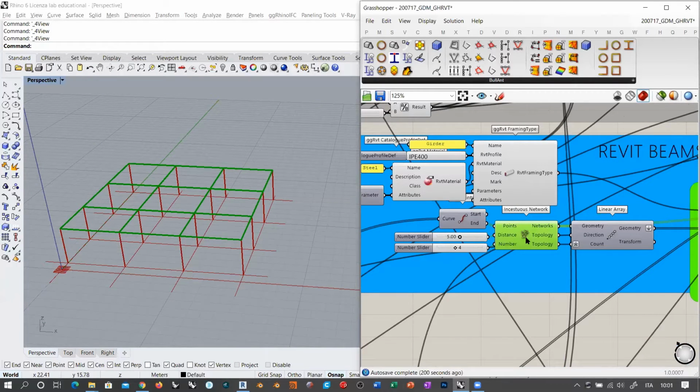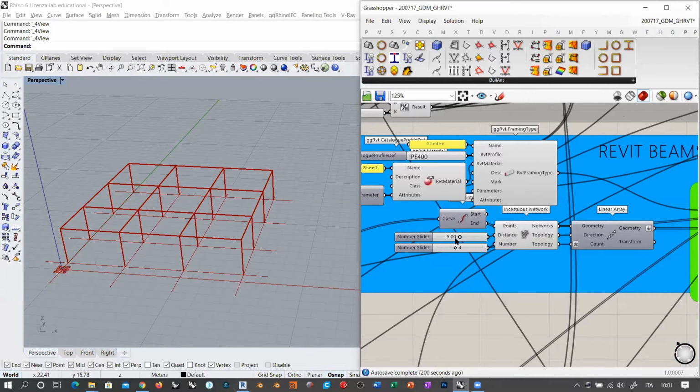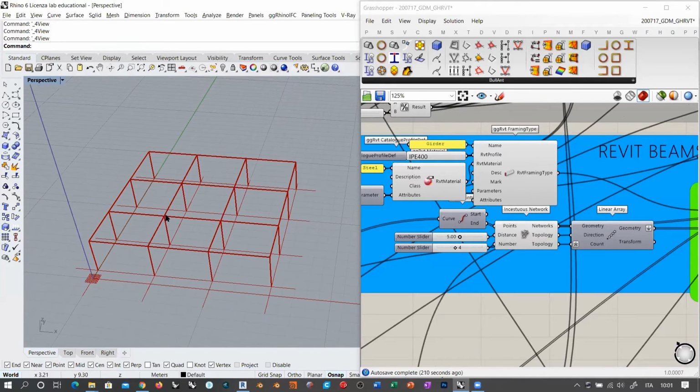I prefer to work with this because it gives you a whole range of possibilities. Okay? Of course, you have to change this parameter accordingly. In this case, yesterday, remember, there was no internal column, so there was no need for creating 4 intersections, but in this case, yes, 4 connections, sorry. And the distance is set to avoid diagonals, okay?